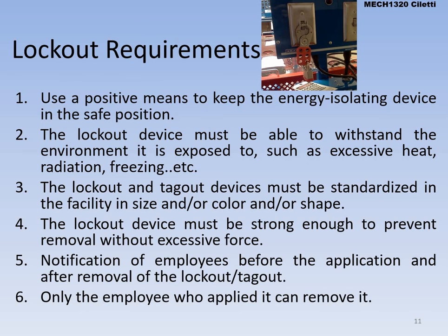Okay, it has to be standardized in the facility, which means everybody in the facility is using the same lockout tagout procedure, using the same kinds of locks. Some companies put your picture on your lock and those sorts of things. So it just depends on where you work. The lockout device has to be strong enough to prevent removal without excess force. Really the only way you're getting through that lock is with bolt cutters. No one can come along and pull it off.